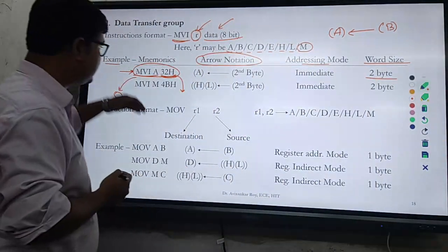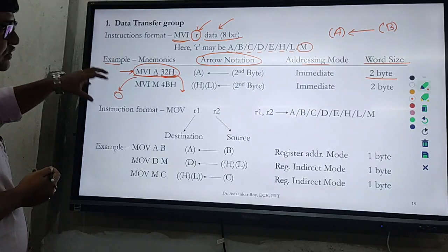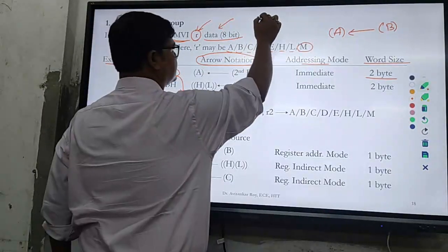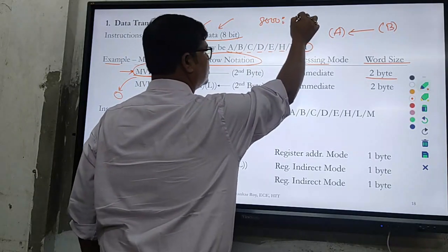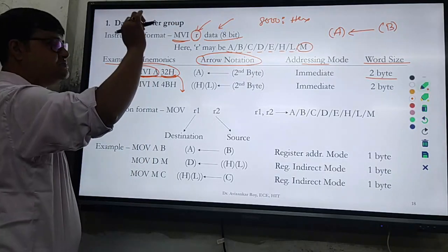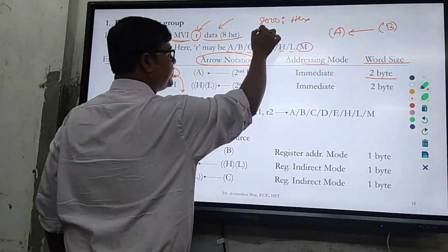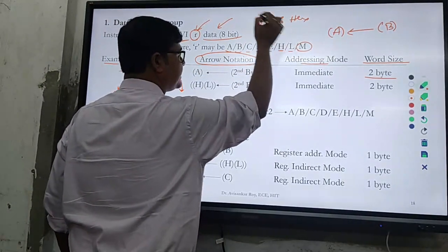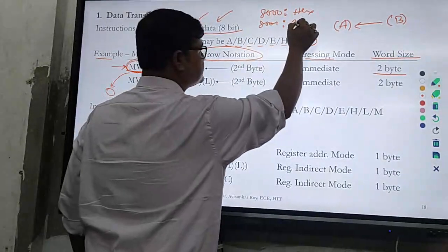So whenever these mnemonics are converted into the hexadecimal code and loaded into a memory location, for example 8000, I go to the 8000 memory location and load the hexadecimal code for MVI. So the hexadecimal code of MVI has been loaded into the 8000 memory location. Now we go to the next memory location, like 8001. Then here we can load 32, the data itself, right?